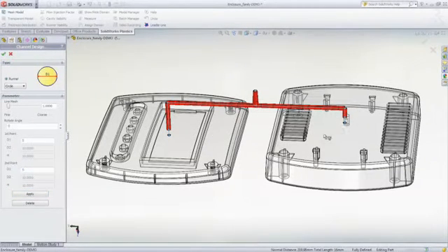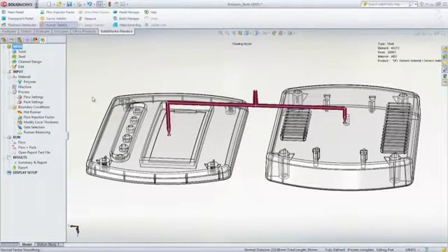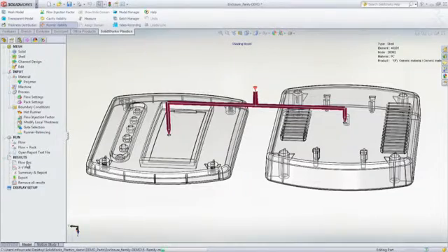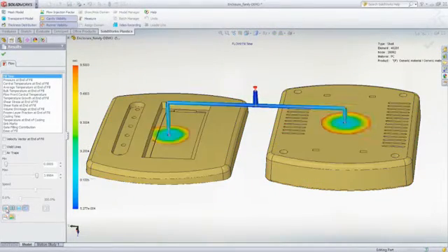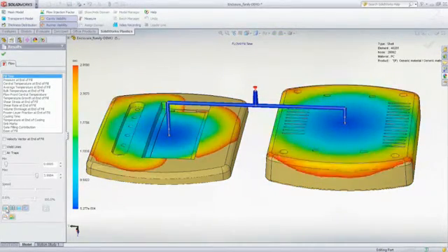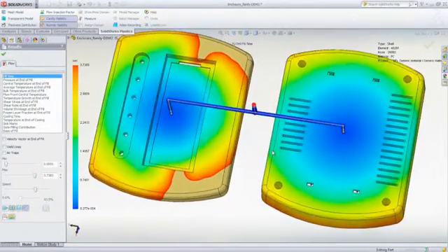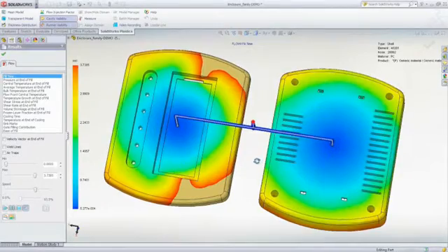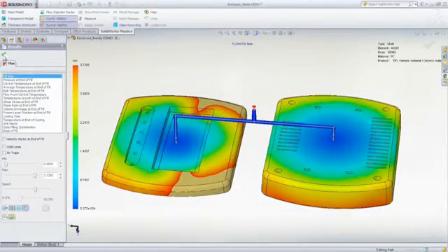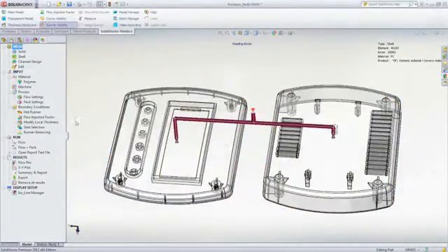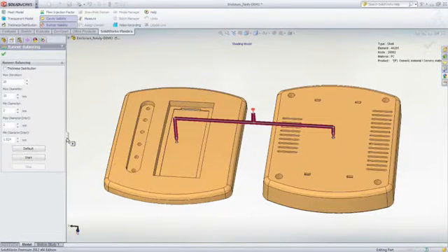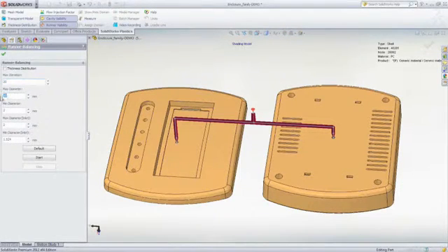However, an additional challenge is introduced because when you mold two or more parts of differing geometry in the same mold, your goal is to get all the mold cavities to fill at the same time. And this can be virtually impossible to achieve without the use of SOLIDWORKS Plastics simulation. The good news is that you can perform a runner balancing analysis in SOLIDWORKS Plastics. This is a multi-iterative analysis with the objective of filling multiple cavities of differing geometry at the same time.